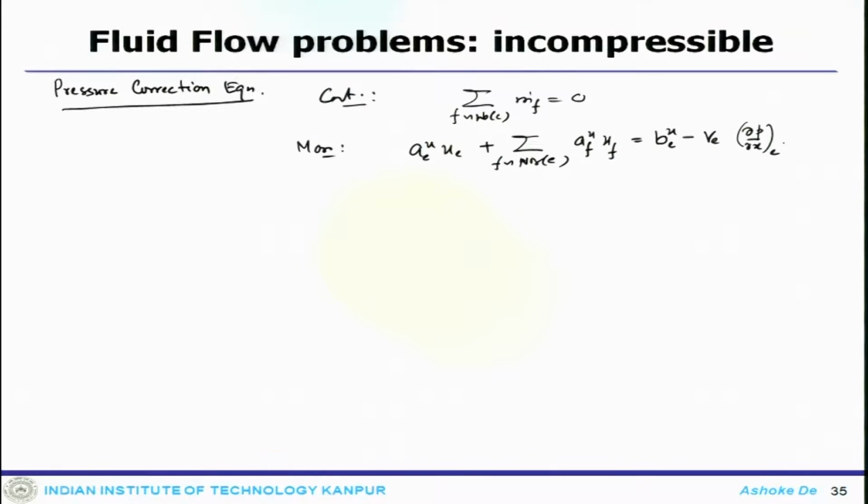Now, the solution actually starts with an initial guess for both the velocity and pressure fields. Once you denote this initial value, the solution at the start of any iteration, with superscript n, the tentative velocity and pressure fields are given as un and pn, which correspond to the nth level of the iteration.